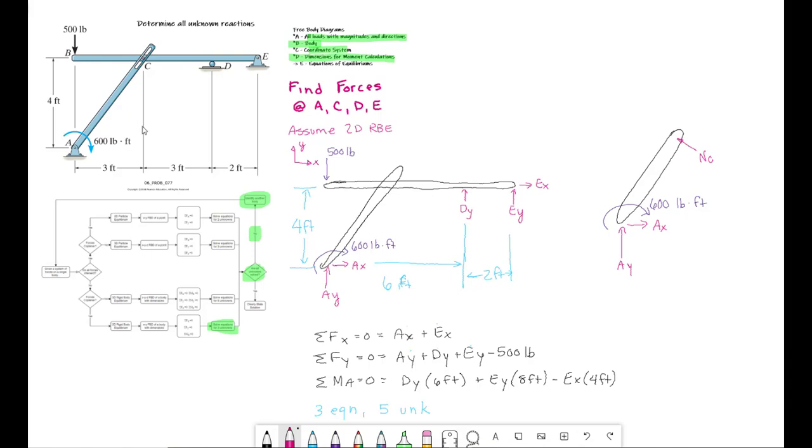You know what? Let's add that note right on there: over, up, 3, 4, 5 triangle on the bar. So the perpendicular reaction is going to take that triangle and reverse it. This perpendicular force here, we're going to switch the rise and the run.